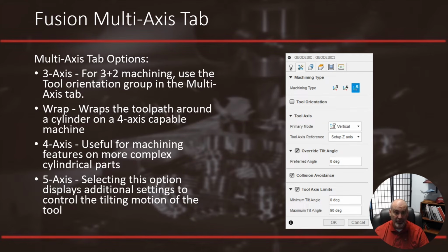And then we have our full 5-axis options. Some commands actually can be operated in 3 or 4. The 5-axis machine running in the 4-axis mode is only going to rotate one of the axes for rotary motion, and could position with the other, but those commands are only effective if the shape you're cutting is very cylindrical and is in line with one of the primary rotary axes.